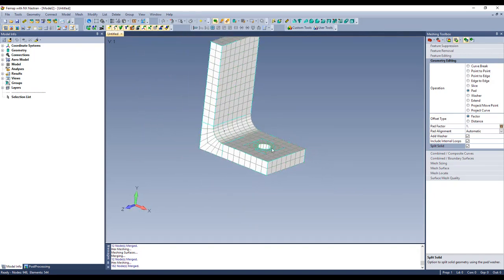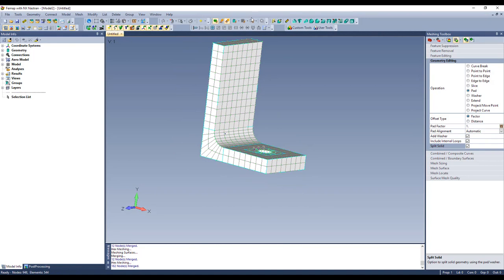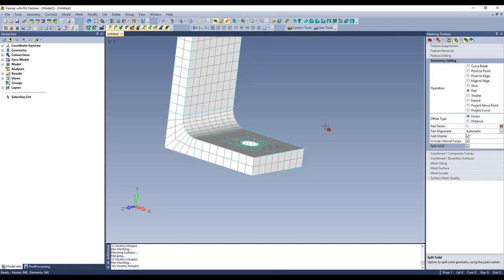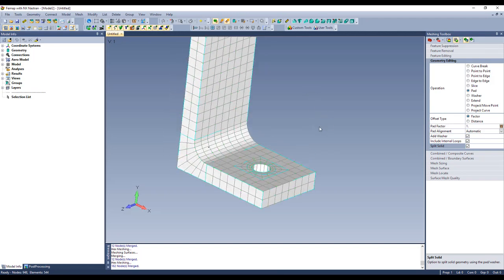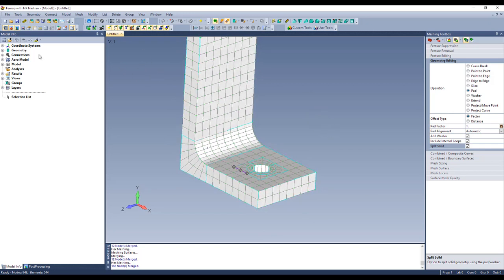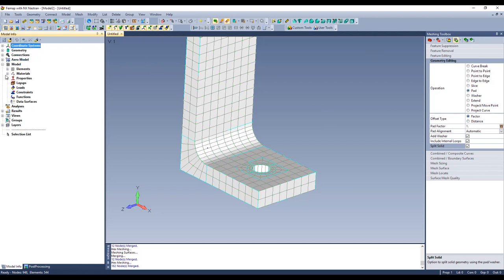So this heel and toe, what happens is when you pull up on a fitting or something, it's going to kind of fulcrum from this edge over here and increase the bolt load. So let's go ahead and investigate that. So first thing we'll do is we need to constrain this. Let me turn off my thing there. I need to constrain it.